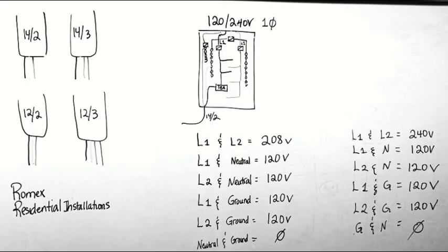We just do the conversion, because when we have to find the value of amps, we can't use the 470 milliamps. We have to use 0.47 to get a correct answer. That was one of the mistakes that I found in a couple of operations done yesterday: because we had, for example, 1.8 megas, they added them as if they were 1.8 ohms, and then we got all decimals, which was incorrect.